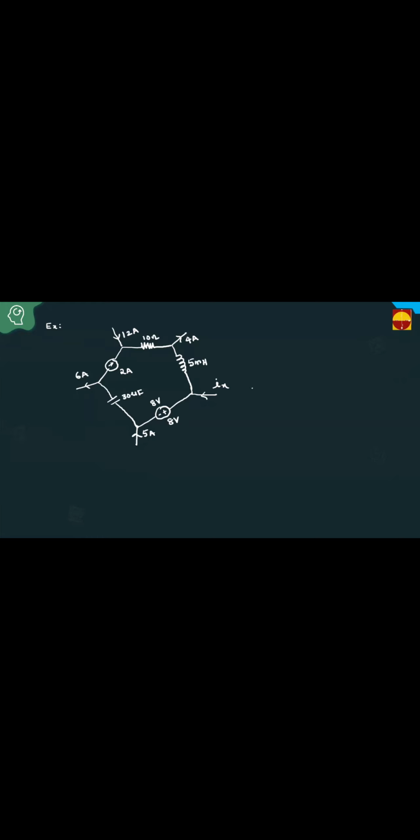How to calculate what is IX? Can anybody answer? You have a fraction of a minute. Come on, do it. Here, how much current is entering? 12 amperes and 2 amperes, total 14 amperes. In this 14 amperes, 4 amperes is leaving here. Then the remaining 10 amperes goes like this.